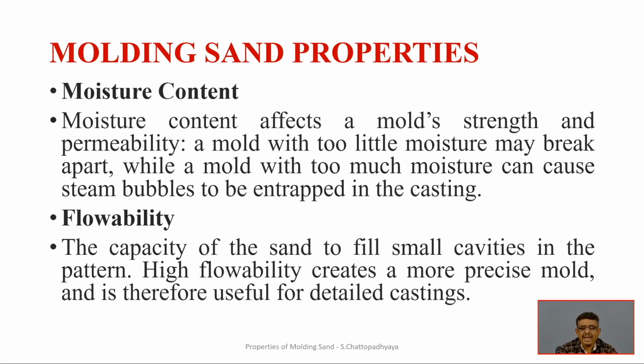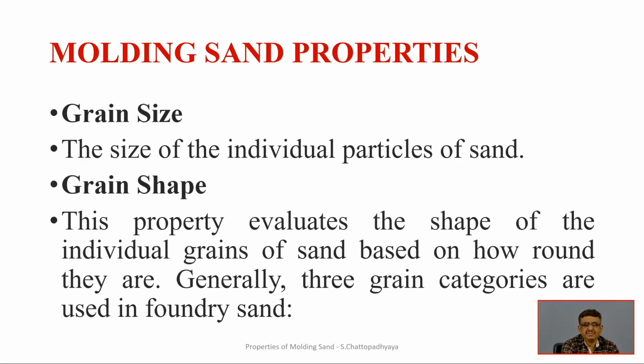there will be sand, and that will only be possible if we can provide appropriate flowability to the sand, and with the ramming and other kinds of activity, the sand will spread across the different complex profiles of the pattern, and in such a fashion retain its strength. Whenever the pattern is withdrawn, those kinds of intricate shapes are maintained. So flowability also has to be ensured. In case the sand has no flowability, then a lot of effort has to be made in order to spread it across and appropriately form the mold.